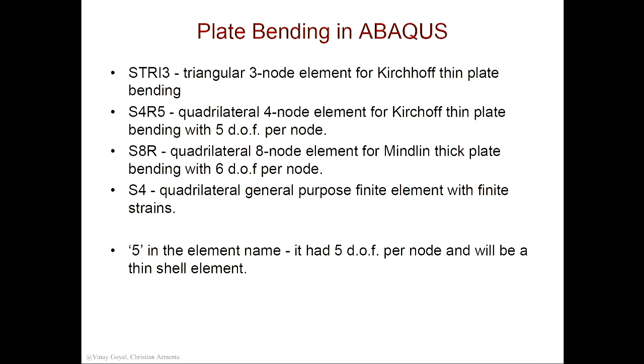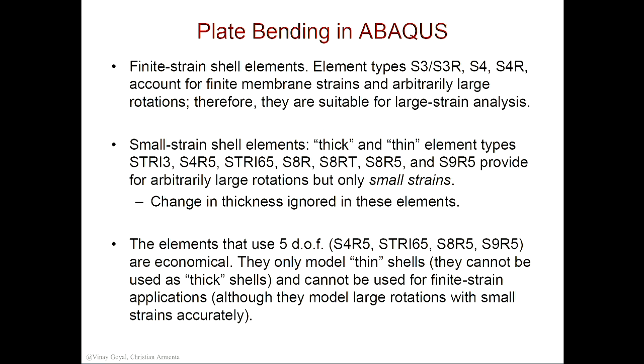These are other element types that can cover thin plates. So if you have a thin plate, you will use something like Euler-Bernoulli, where Euler-Bernoulli is similar to Kirchhoff thin plates. I didn't cover that here. I did Mindlin plates. All right, you guys can read that.